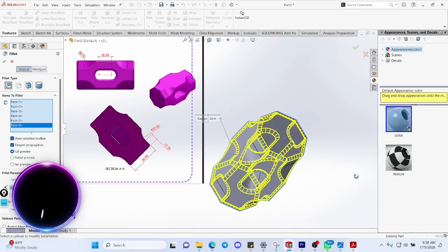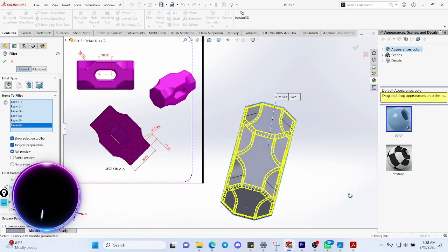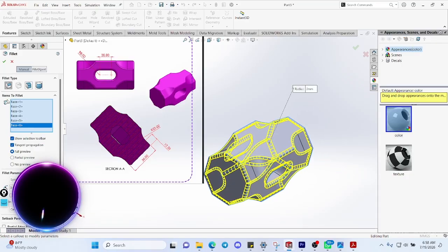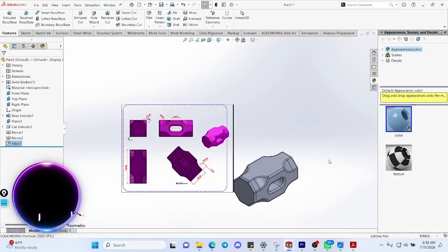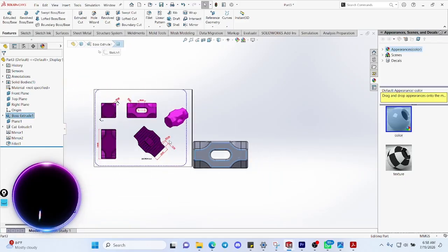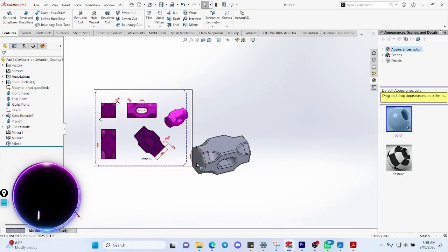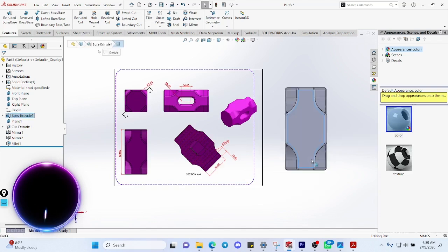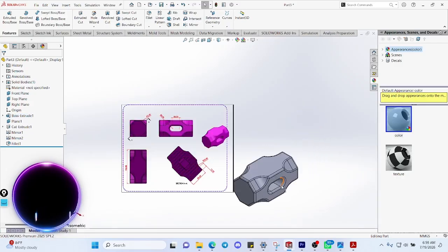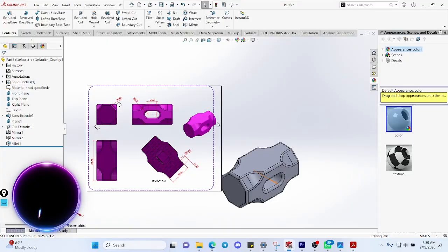Clicking on the faces is easier because it selects all the connected edges for you instead of having to do that yourself. So you click good. So you can see we've successfully created our sketch. When you look at it from the side plane, Control 8, look at your side plane, it's looking exactly like this. When you look at it from this side, exactly what you see here. When you also look at it from the top plane, Control 8, look exactly what you see here. When you look at it isometrically, this is exactly what you see here.